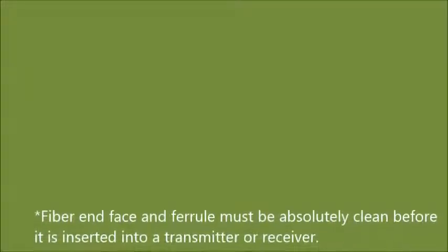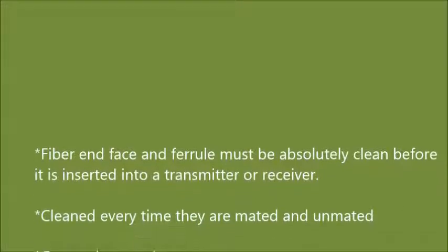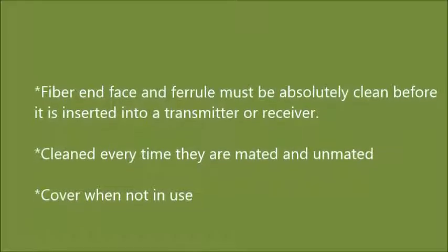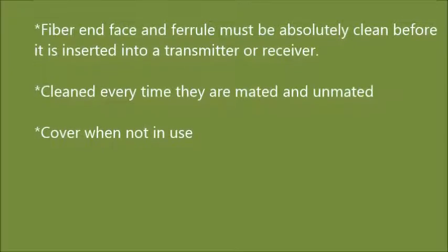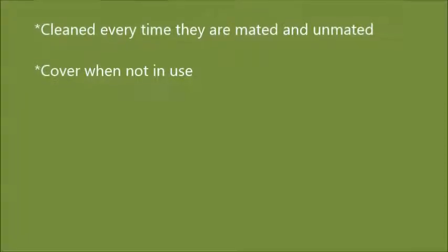There are some methods of care and handling the fiber optic connectors. First one, fiber end face and ferrule must be absolutely clean before it is inserted into a transmitter or receiver. The dust, lint, oil, and other foreign particles that obscure the end faces must be removed. Second one, fiber optic connectors need to be cleaned every time they are made and unmade. Third one, it is also important to cover a fiber optic connector when it is not in use.